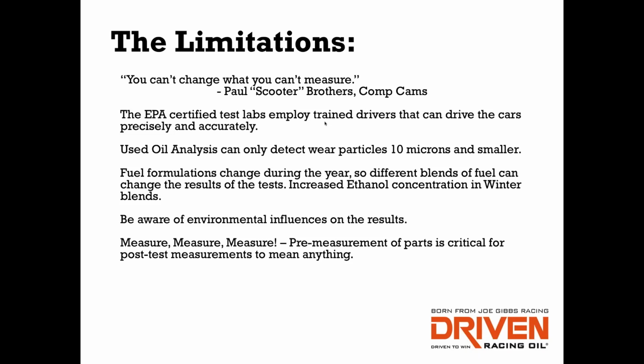The fuel change had that influence, which again leads you to look at all the environment. Pay attention, in your specification and in your area, to what things might be having an environmental impact. The temperature of the measuring equipment has a big impact, seasonally. The same measurement in a cold room is going to be different than in a hot room. So keep those things in mind.